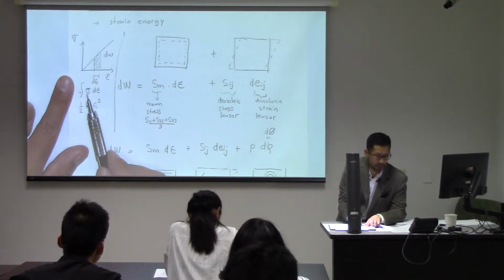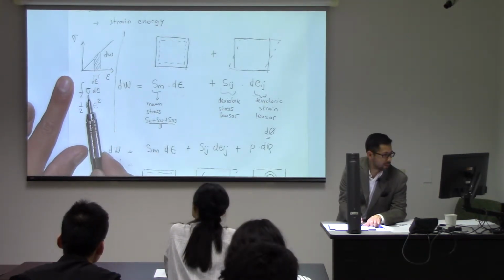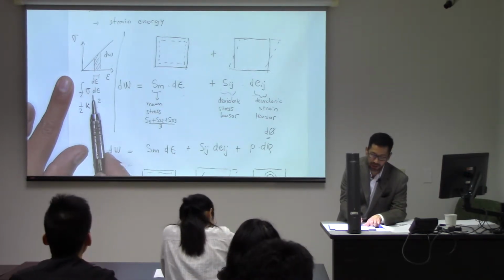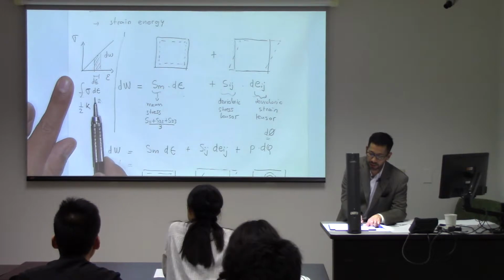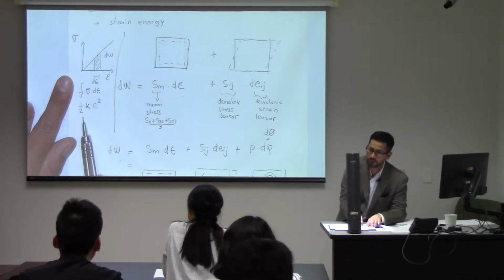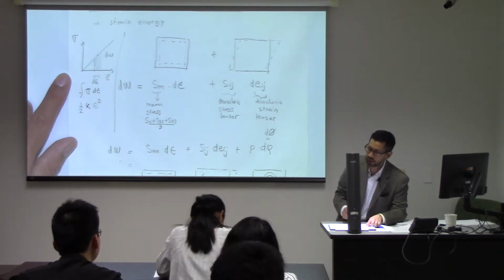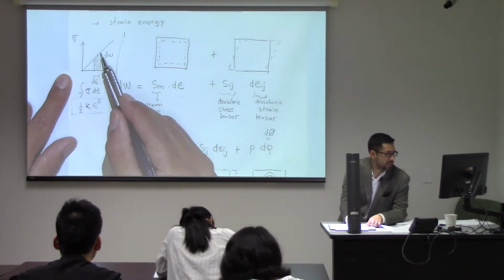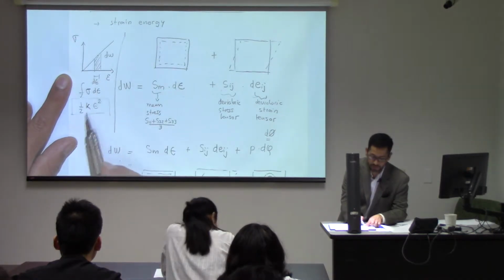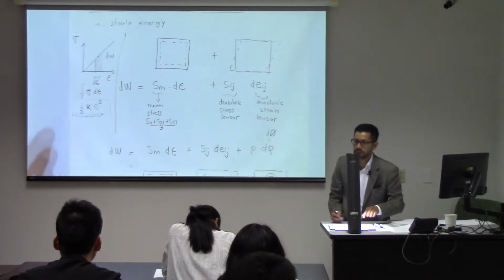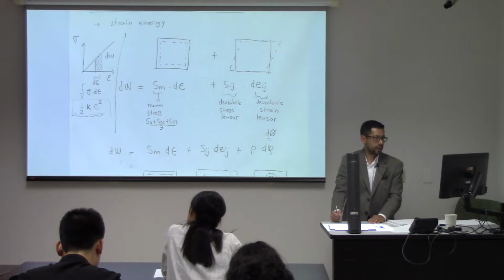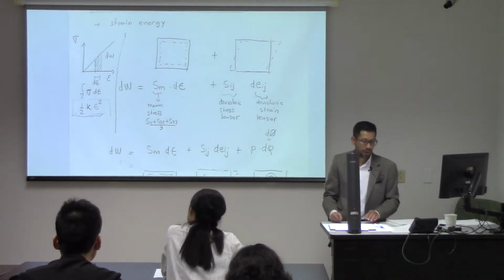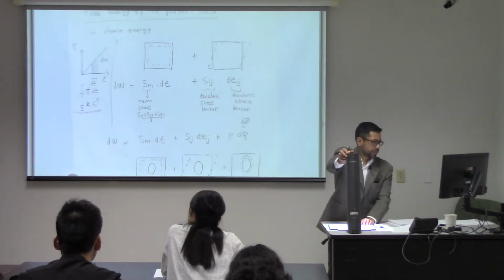and if you assume an elastic law where sigma is k times epsilon, the integral of that is going to be integrating on epsilon. It's going to be epsilon squared divided by 2. So it's just an integral. So at any point over here, the total energy is this number over here. Strain squared times, in this case, the bulk modulus. Okay, so